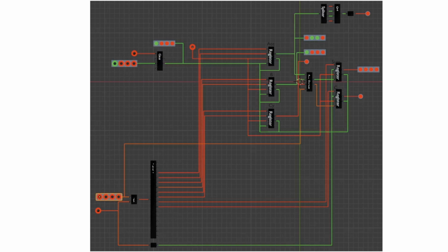Note that the operator is always active and the results change even if the operator is not needed. The actual command execution only takes place when the results are written into the sum and C registers. The correct result of 14 is now in the sum register and in the C register, which is deleted. Since the ADD command provides the result in the ACC and CY, we still have to write them there.